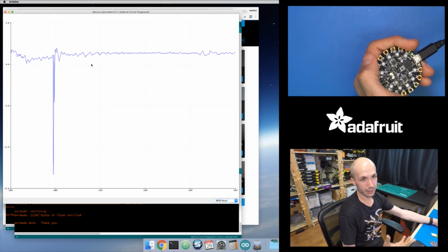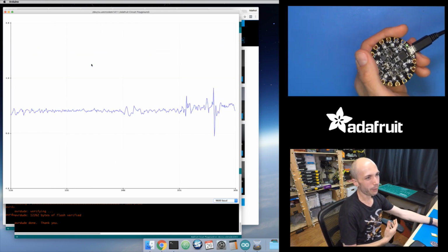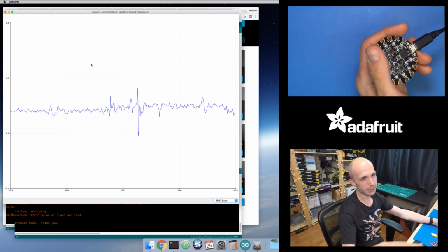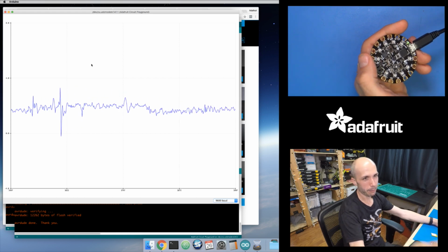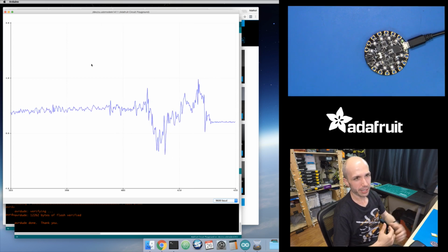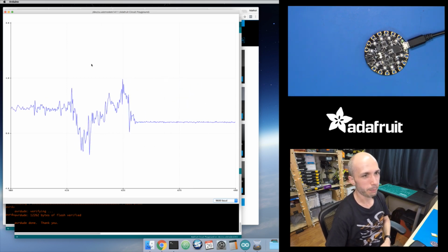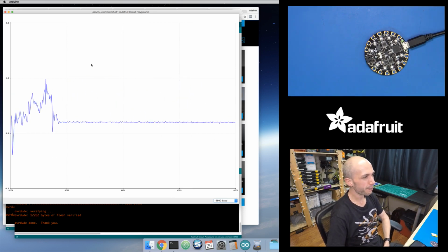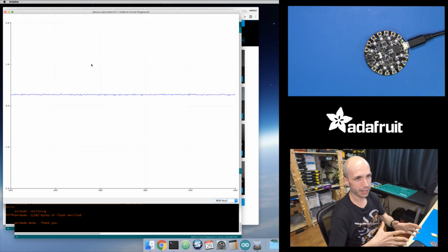So that's another challenge here. I want to detect that initial spike, but I don't want to detect when it comes back. I don't want to detect that as another spike. So I want to debounce that logic, or stop listening for a while. I just want to capture that initial spike and then go from there. Now, the big question then is, how do you detect that peak?